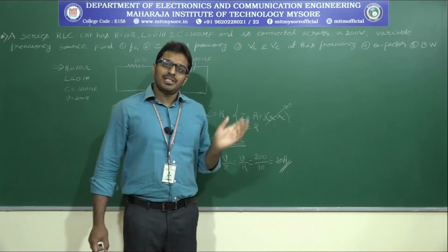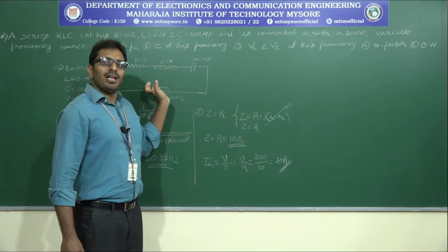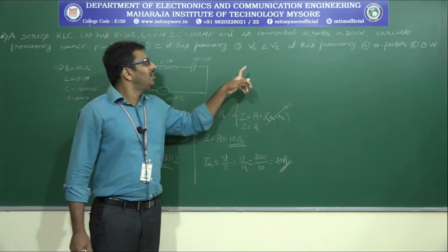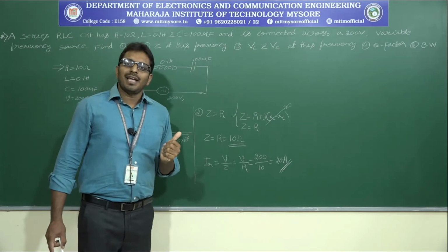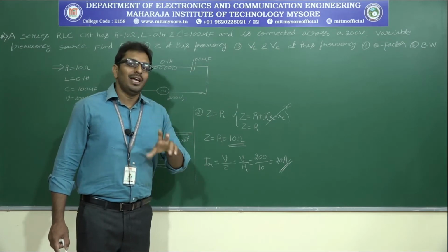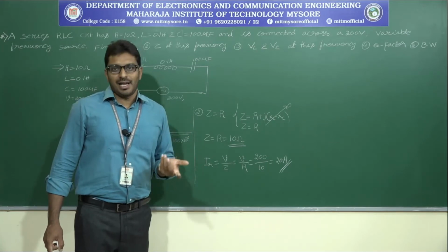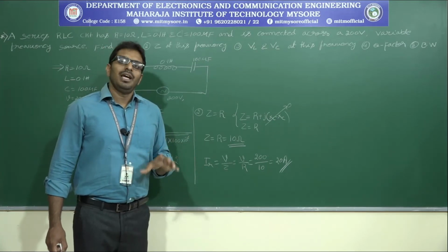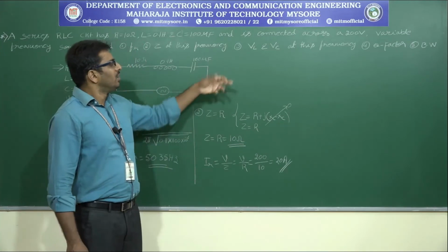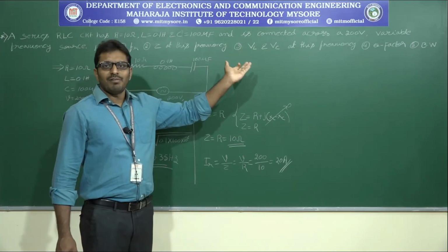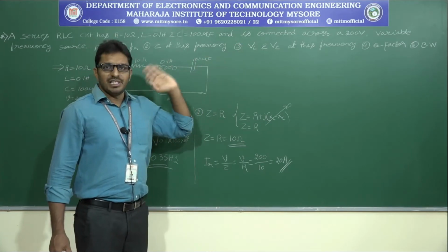The same current flows through these two elements, so when the same current multiplies the same values of XL and XC, obviously VL is exactly equal to VC. VL and VC values are equal but in opposite directions. That's why VL and VC are equal and opposite. Therefore, just calculate either VL or VC, then both are equal.